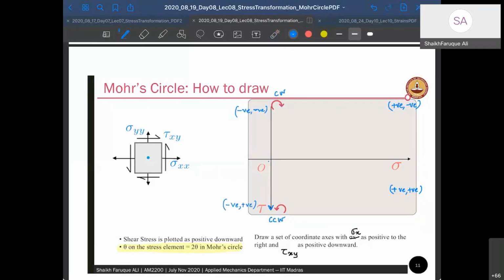All right. Remember the shear stresses are always complementary, so they act in pairs. If the shear stress creates a counterclockwise moment, it is drawn on the bottom side. If it creates a clockwise moment, it is drawn on the top side. So let's look at it. These two shear stresses, this tau xy, what are they creating?